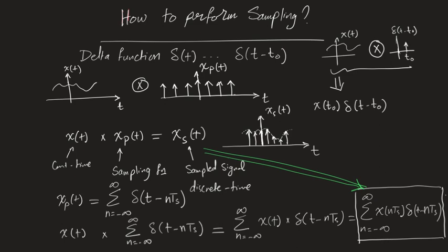Now what prevents me from making them very close to each other is the fact that I'm going back to the problem of continuous time signals, that I have too many values, right? The problem of any continuous time signal is that between any 2 points, you have an infinite number of values. It's a continuous line, so it can be broken into an infinite number of points, right? So if I make those samples very close to each other, I end up with a huge amount of data that's going to be prohibitive in terms of dealing with it on a computer.